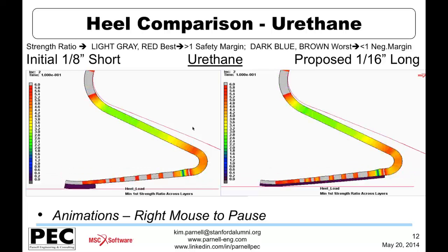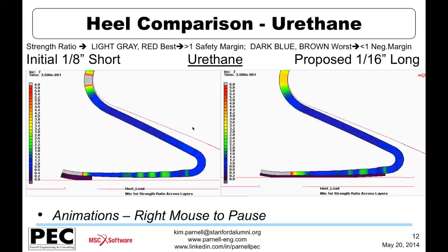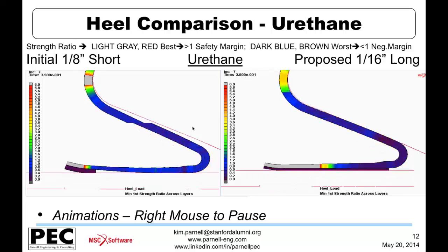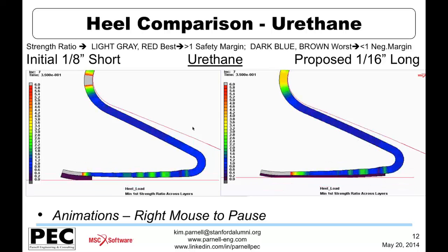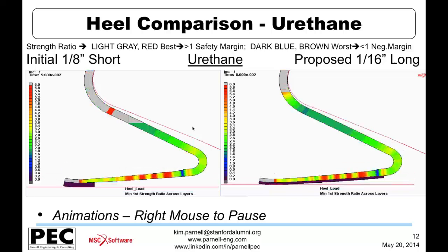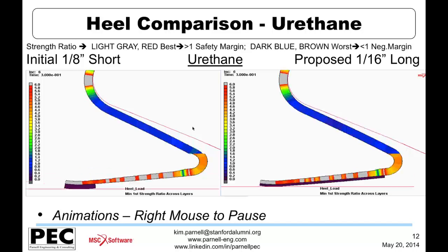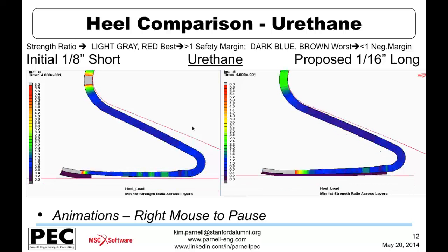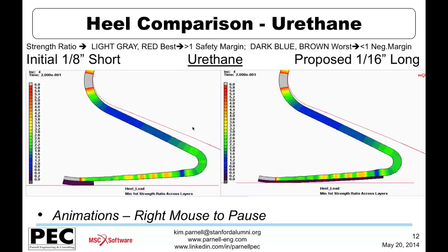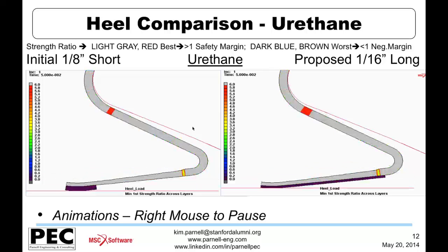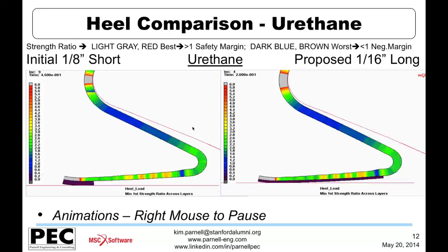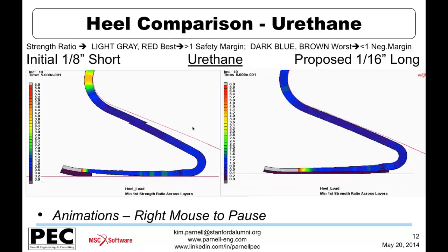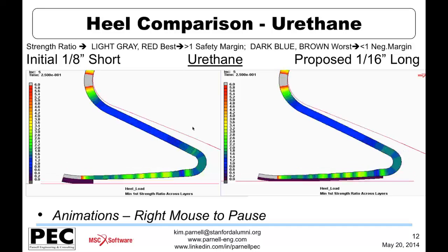So you can establish a specific failure criteria or assessment criteria like Tsai-Wu criteria, and then evaluate a strength ratio from that. And the strength ratio is a scalable component, and it really gives you a direct read on the factor of safety relative to the strengths that you have specified.